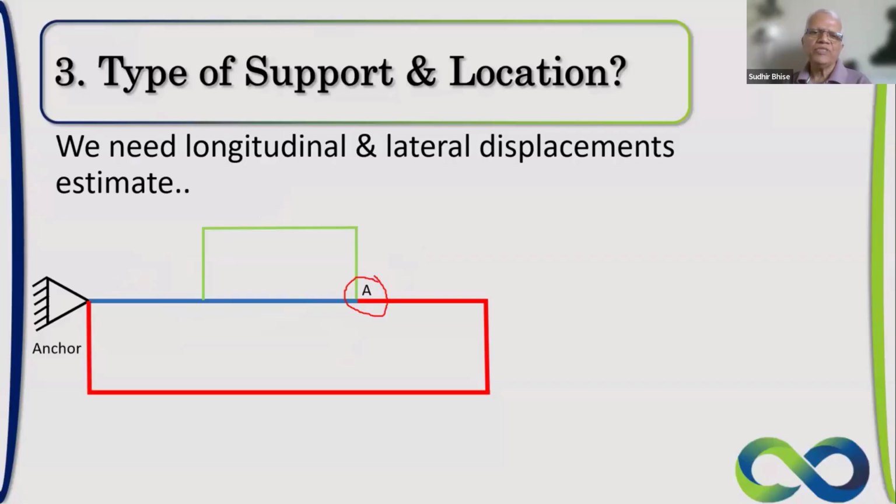Now, can we apply the same logic to the red one also? Yes. Here we can see that the expansion of this leg in this direction is going to be compensated by the expansion of this leg in this direction. And this total length of red is nothing but an algebraic combination of this leg and this leg.